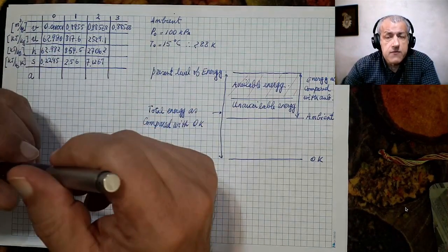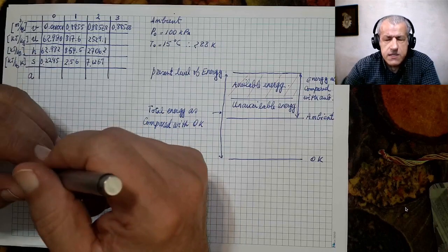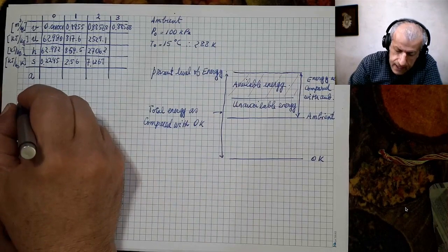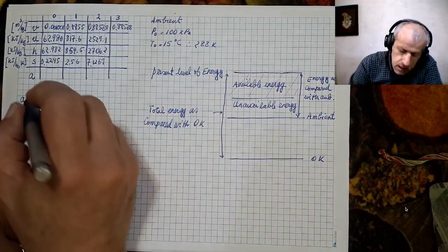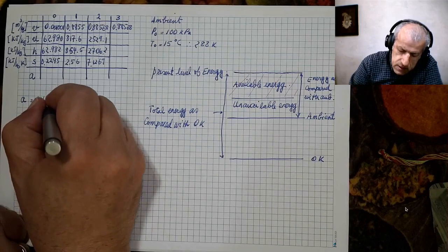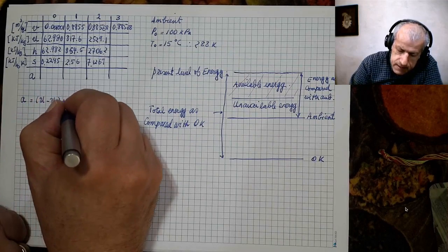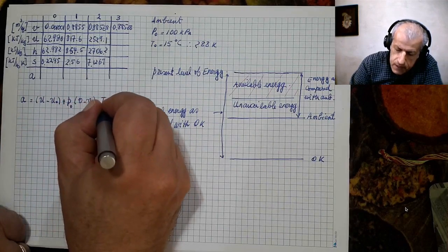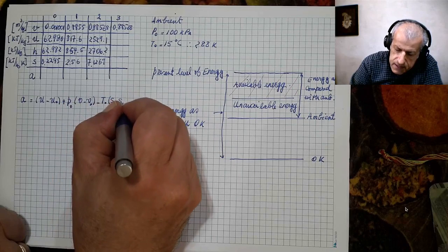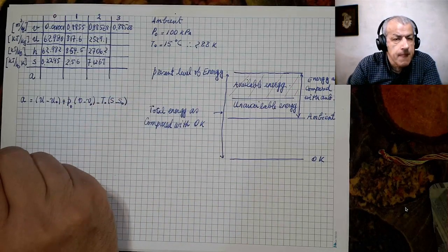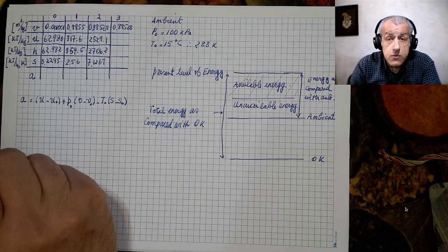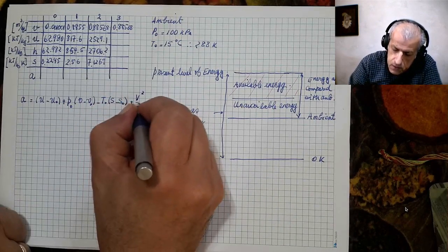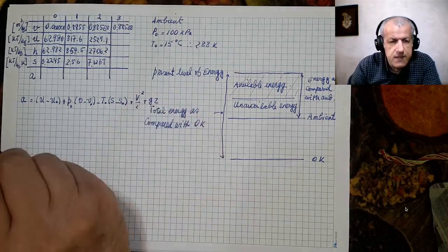A simple equation for that energy is given in just every textbook, and what we have for it is that A, which is that energy, is U minus U0 plus P0 times V minus V0 minus T0 times S minus S0. There are two other sources of energy which could be turned to work, and that is plus V squared over 2 plus GZ.